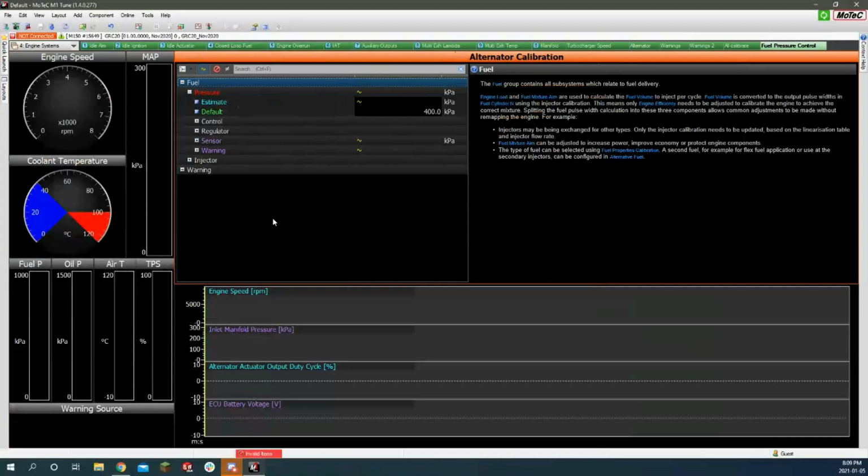If you're running near the stoichiometric air fuel ratio, so 14.7 for gasoline, about 9.8 I think for E85, it creates a lot of heat. You want to run rich when you're at high power to cool things down. It also decreases emissions and stuff. Not that we're worried about that, but yeah, that's a big one. If your fuel pressure drops off unexpectedly and you're at full power, that can be quite bad for your engine. So that's a common warning that we might set up.